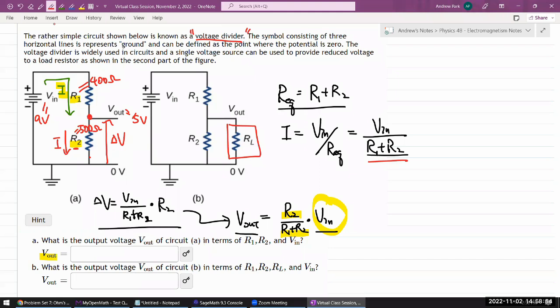It's showing you the setup where this output voltage is connected to something that draws some power, does some stuff. So there's a load resistance. Let's redo this calculation and see how the expression for V out changes. We can do more or less the same analysis we had before. I need to insert an additional step here to calculate what I'm going to call R2 prime. It's the equivalent resistance for these two resistors in parallel.